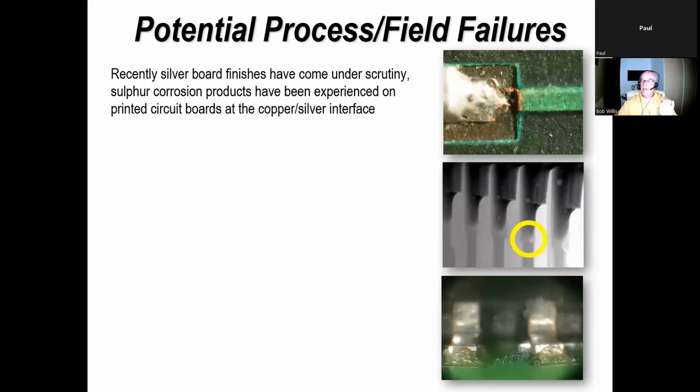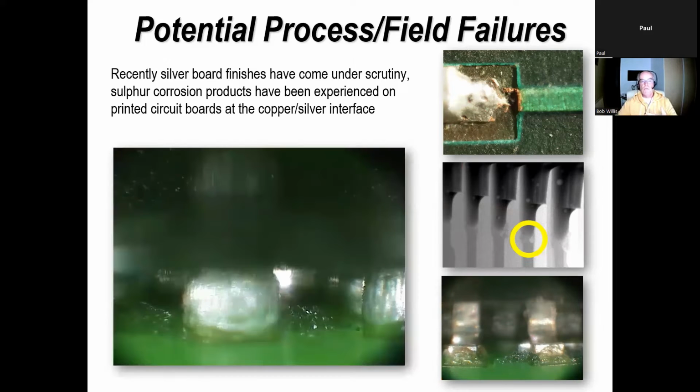So one other area, hopefully, that conformal coating can assist with is gaseous environments. Now, when you've got a gaseous environment, particularly sulfur, in combination with a silver surface, possibly on a PCB or a termination, it can actually corrode over time. So classic examples of that is products working close to a pulp mill where there's a lot of sulfur in the air. Possibly a product that's working in an environment where there's lots of volcanoes, where there's lots of sulfur. But what you're looking at here, top photograph shows a track has been eaten through by sulfur corrosion. The X-ray image, second one down where I've circled, is partially dissolved tracking. And conformal coating can protect products to a degree, but again, it needs to be quite a thick layer.